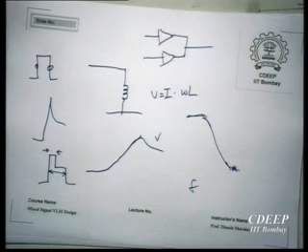The other part is that actually when you are sending data, somebody is generating this, right? There is no point in making an interconnect which is capable of operating at a speed which is much higher than your logic. A little bit is okay, but don't be too greedy and use up a lot of power to prove that I have got an interconnect which works at 4 gigahertz. However, unfortunately, I can't go above 2 gigahertz for my clock. Then what's the point of having a very fast interconnect, right?